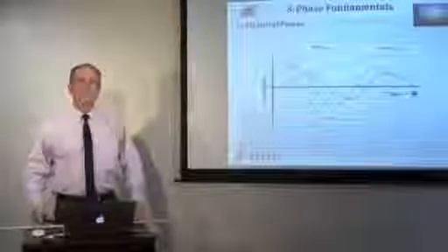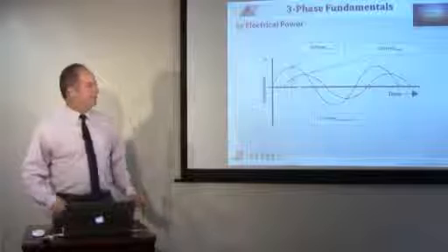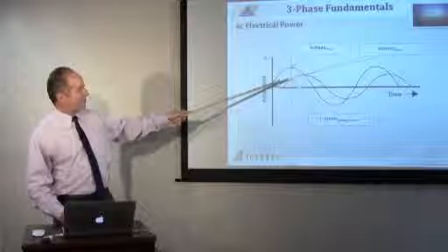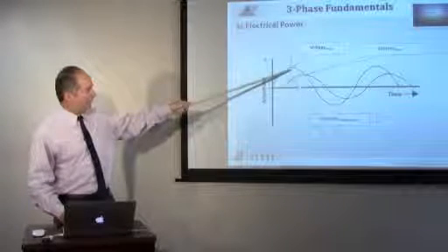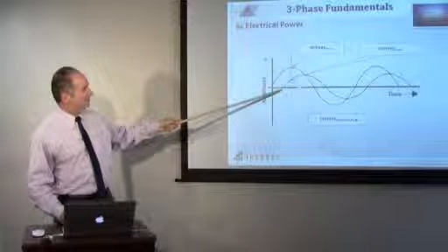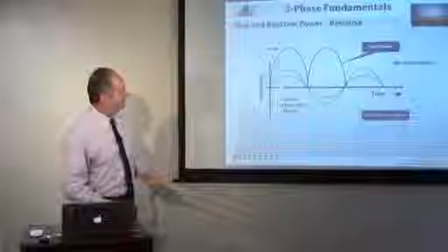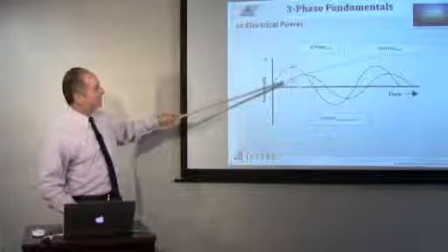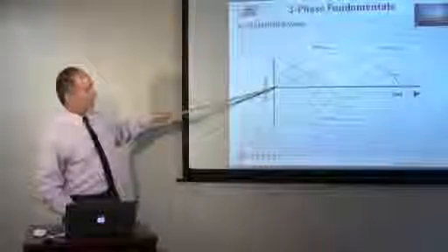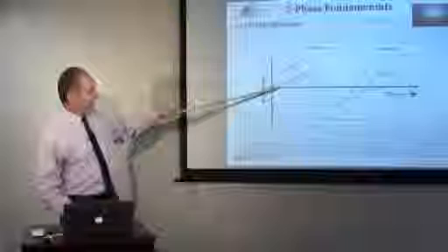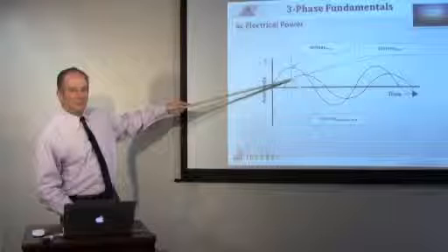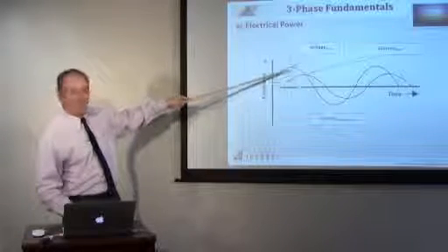Now, taking this a step further, if this is the current at the time of peak voltage, and this is the real power, the watts, and we are lagging so much, then if we could add a capacitor to move this forward, a capacitor causing leading current, the peak current will only become as high as the load requirements.